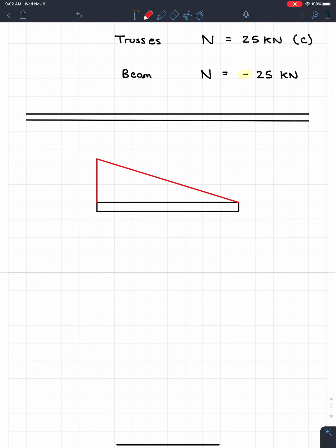So we write 6 kilonewtons per meter. We know that this distributed load will create a single force at a distance here. So I'm just going to put this here. I'm just going to call this F1 for now. I'm going to label my point C because that's going to be very important to us later. And finally, we know that we have a bunch of unknown support reactions. So over at B, I'm just going to put a single roller. So this is going to be BY. Over at A, we got a pin. So we're going to have a vertical and a horizontal force.